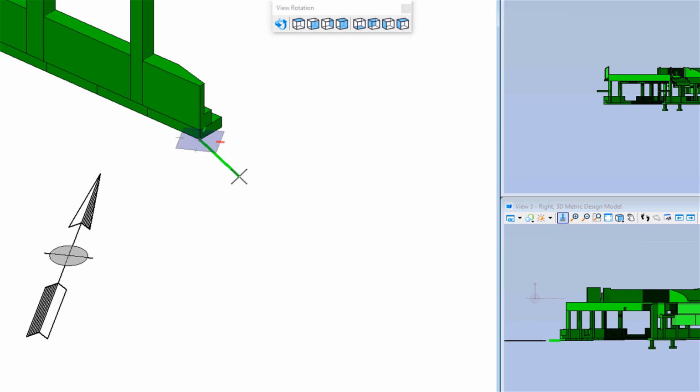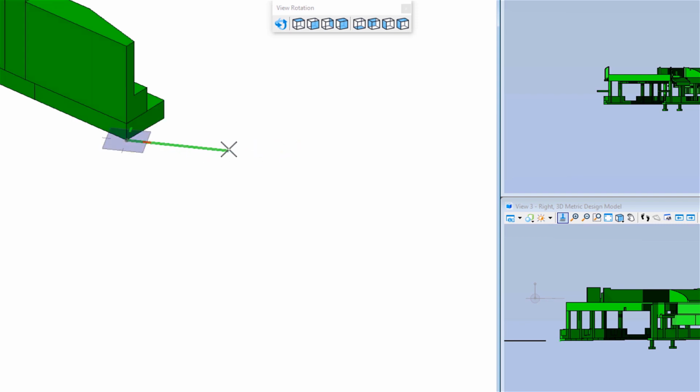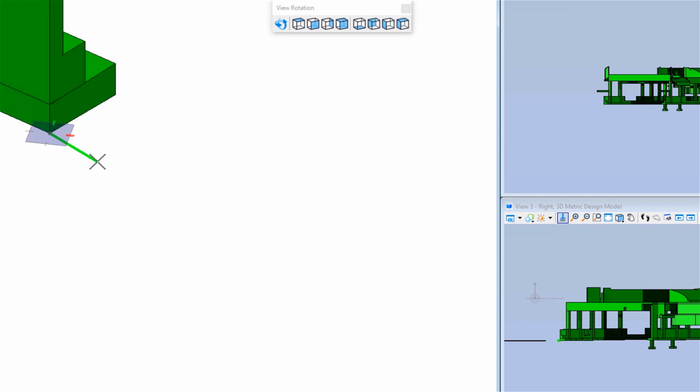Now, being in a rotated project area, you can see north is true north, and our project isn't perfectly orthographic to north. So this is most common in projects drawn coordinate correct. What I want to do is line my compass up. So I'm going to zoom in a little bit here, and I want to line that Accudraw compass up so that I can draw flat to this slab, or planar. So I'm going to use a two-letter shortcut.